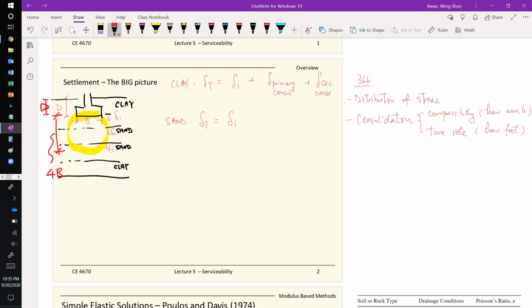So for sand, only for sand, not for clay, those consolidation deformations are relatively insignificant compared with the immediate settlement. In fact, once we place the dead load on the sand sample on the direct shear machine, the settlement or deformation there comes from the immediate settlement.